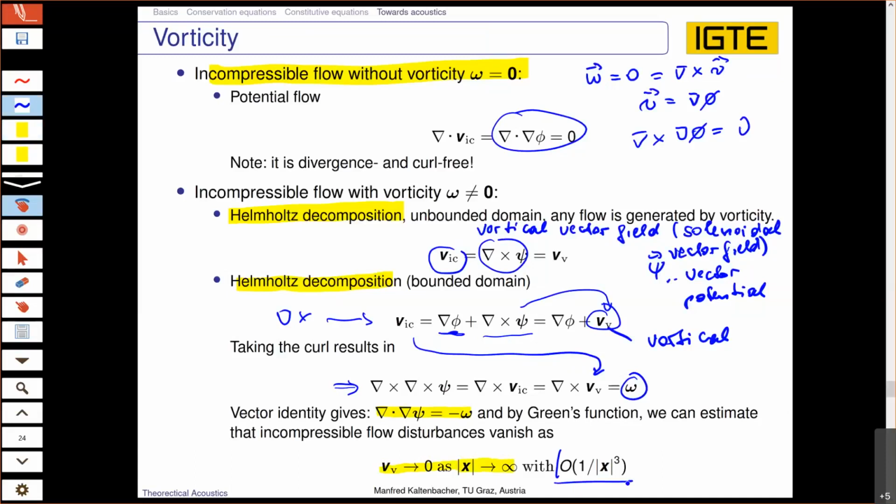And we will see that the wave structures decay by 1 over distance. So you see that in most cases, and that is the good news for us in aeroacoustics, we can restrict the computational domain where we compute the flow, where we compute the vortical structures, which will be somehow the sources for generating the acoustic waves. And we have to compute the acoustic field in a quite larger domain, because there the decay of the amplitudes of the radiating waves just decay with 1 over distance.